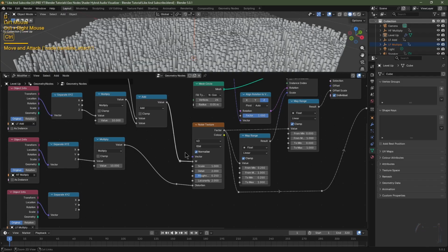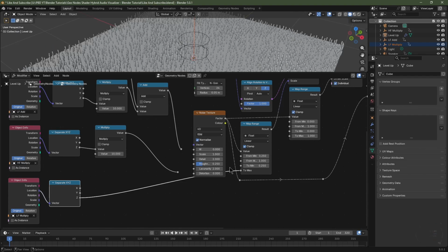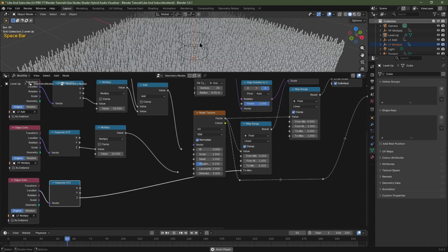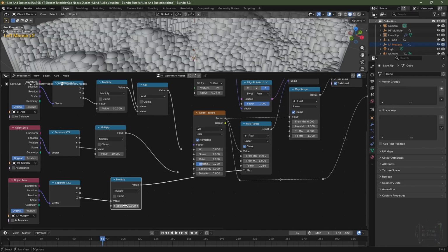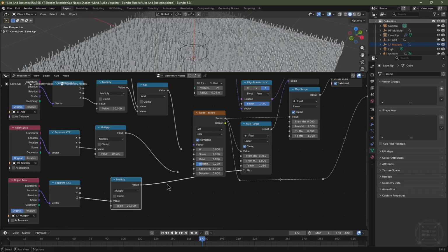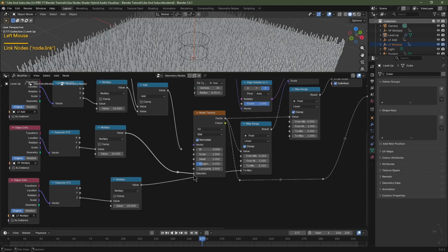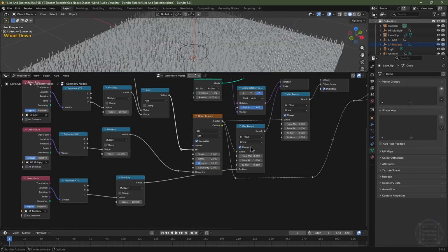I'll then hold down Control, right click and drag through these two noodles, and that will disconnect them from the loop. I can then take this Z location data from the low frequency multiply function and plug it in the 2 max on the map range node. I'll then hit play, and you can see the effect it's having there. I want this effect to be a bit more predominant, so I'm going to take this math node, I'm going to hit Shift D to duplicate, and I'll pop this down here, and I'll change the value to, let's say, 20. I'll just hit play to preview that. Okay, excellent. I can now reconnect this math node into the distortion socket, and reconnect this math node into the W factor. I'll just skip back to frame 1.